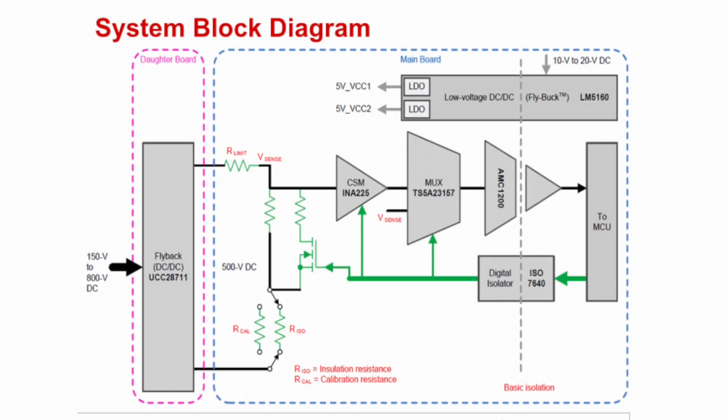The block diagram for this design shows that the leakage current is measured by applying a fixed voltage and measuring the voltage across a shunt resistor that is a result of the leakage current. The reference design uses different switchable shunt resistances, which are switched on in a sequence to measure the insulation resistance. When there is a dead short, the insulation resistance is 0 ohms, and a maximum current can pass through the insulation. At this point in the measurement, having a smaller shunt value is mandatory with a multiple shunt approach. When the insulation is higher, a larger shunt value is required with a single shunt approach.